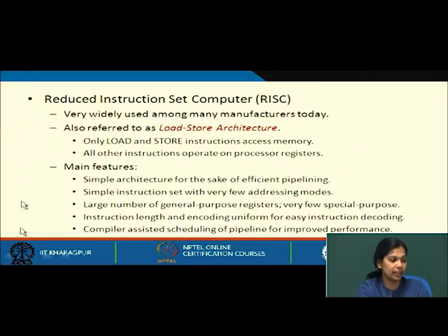Instruction length and encoding are uniform for easy decoding. See, if you encode all the instructions in a specific fashion, then the decoding will be much easier. And compiler assisted scheduling of the pipeline for improved performance will be there. You will see this particular feature more in pipeline.